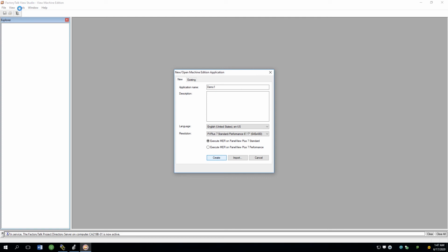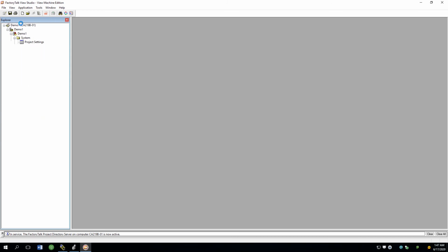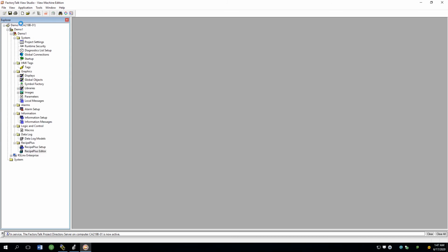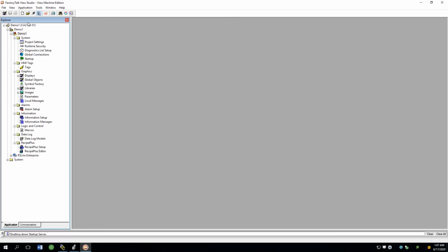And over on the left panel here, it's going to create the Explorer window. The Explorer window allows you to configure many different settings for the HMI. It's very much like the Explorer window in the PLC software. And this takes a little bit of time, and what we're eventually going to do is, first of all, configure the communications so that the PLC can speak with the variables that we're going to set up in this program. Okay, so the HMI communicates with the PLC. So it seems like this is stabilized. So wait till it does. Wait till it stops flashing.